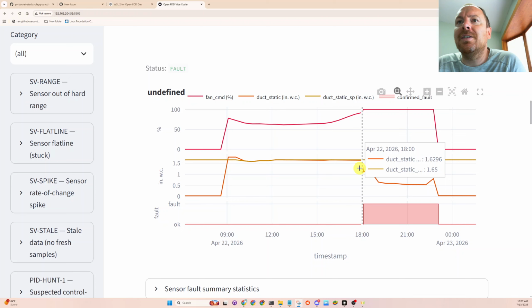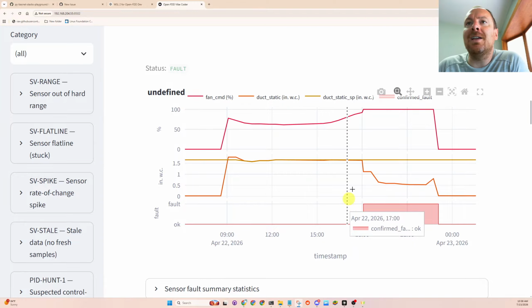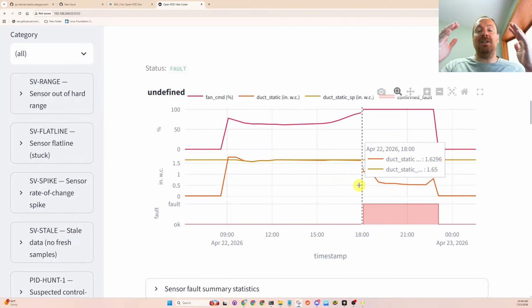More than likely late in the afternoon. So this is 1800 hours. So yeah, very late in the afternoon. More than likely the building just requires cooling, and perhaps the chiller wasn't running yet. And when the VAV system, when the air dampers and the duct system start opening up because they need more cooling, duct static pressure drops, the fan attempts to go up to full speed, and it can just not maintain that static pressure.